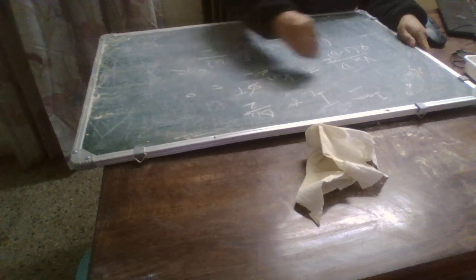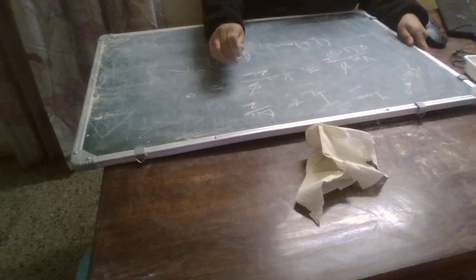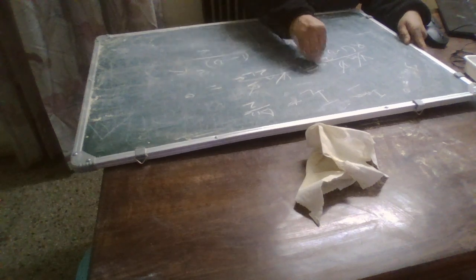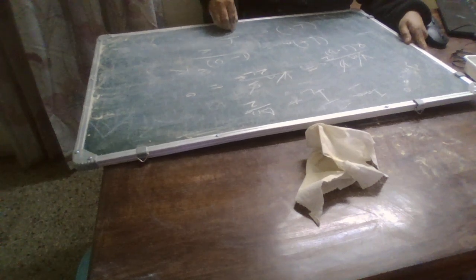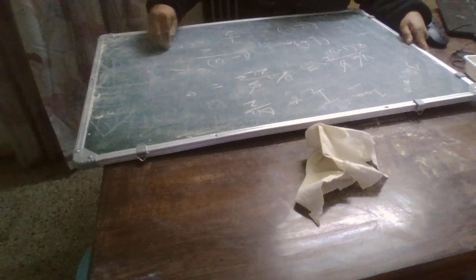Now this D will get cancelled. Let me put T as 1 by F. This is LF. This input is again going to get cancelled. So if we just rearrange it, we are getting LF equal to 1 by 2, this R, and we will take up here R (1 minus D) squared. So this is the expression that I have got here. This is the minimum inductor current that should be there to avoid going to the discontinuous mode, because this is a continuous mode of operation.